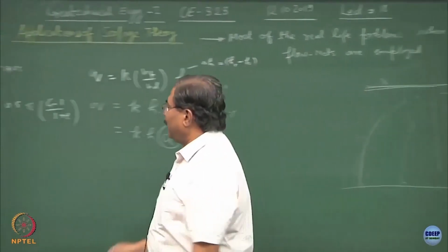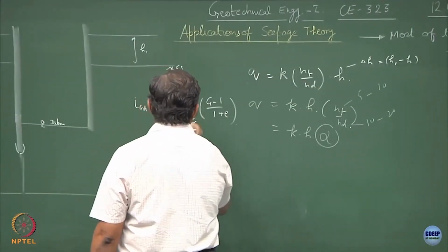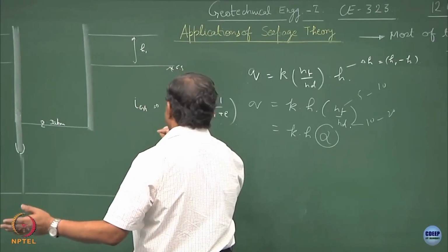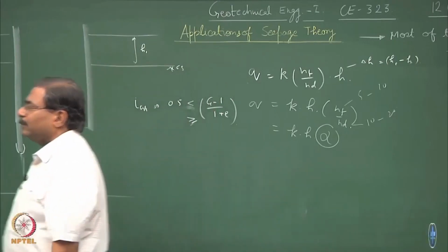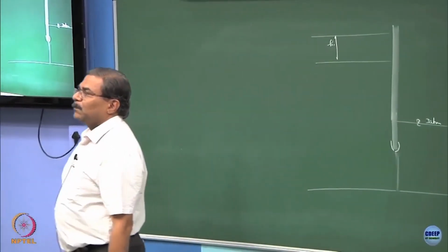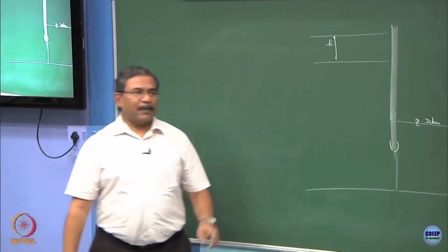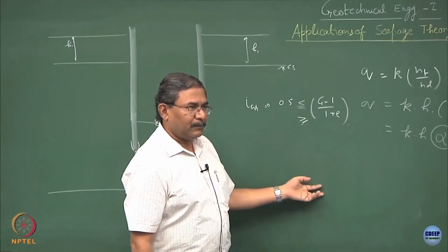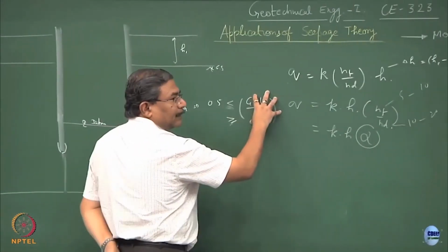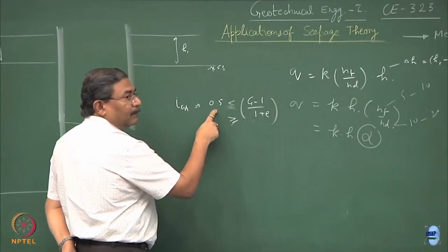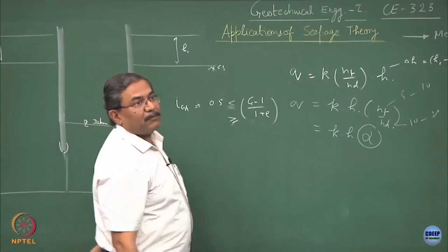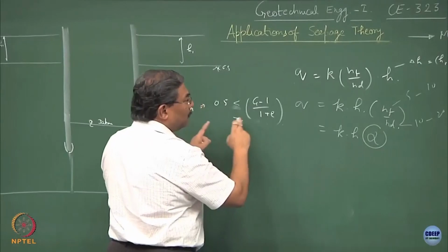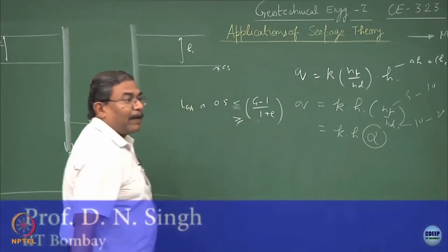And suppose I say this is less than or equal to, or greater than or equal to, another case, what is the implication? Just by using these signs I have changed the implication of the entire situation. If the theoretical i critical is more than the exit gradient you are getting, your sheet pile system is working absolutely all right. In the other case, the exit gradient is going to be much more than the theoretical one, and it appears that piping is going to take place.